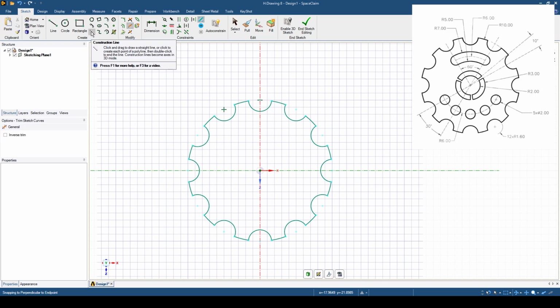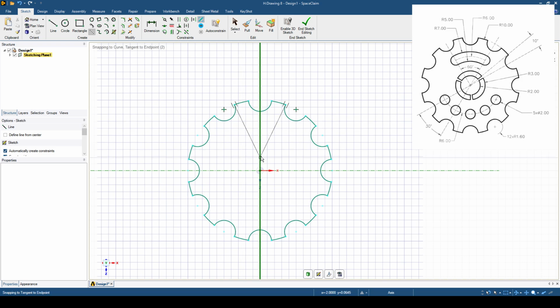First I go to construction line, and as you can see, the radius of the arc construction at this location has a 6 mm radius. That means 6 mm away. So we can do the following. I will start from the origin. I will click, and as the length I will type 6. Before this, I already have 30 degrees down, so it's right. But in case you don't have 30, you click Tab, then type 30 degrees and then Enter.